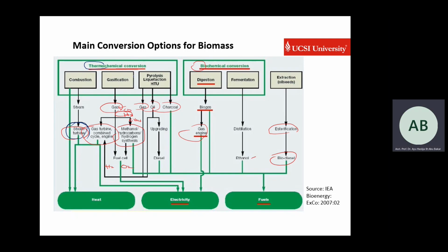Then for gasification, it produces gas, producer gas or syngas. From these gases, it can be used to supply to the turbine, where the turbine again will produce electricity. The gas produced from gasification can be used also as fuel cell. For the fuel cell, the gas specifically will be H2, to supply the fuel to the fuel cell. Then from the fuel cell, it will generate the electricity as well, the voltage, the current.